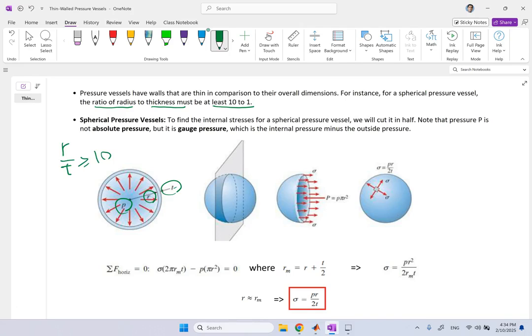And P here, before we move on to stress calculation, P here is gauge pressure. It's not absolute pressure. So this is measured with respect to the outside ambient pressure. Okay, so P here is the difference literally between absolute pressure inside and the absolute pressure outside. This is a gauge pressure. Okay, it's a relative pressure to the ambient. So that's why from outside we did not put any air pressure, because by considering this relative, it's basically like canceling this component. Okay, so keep that in mind.